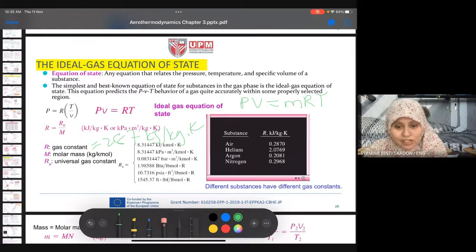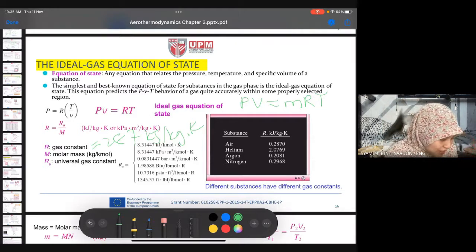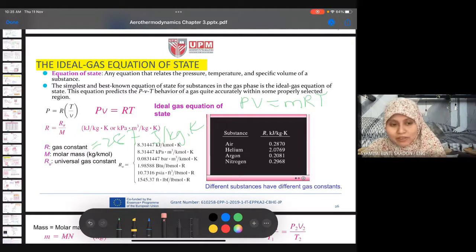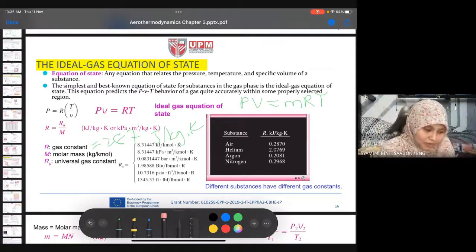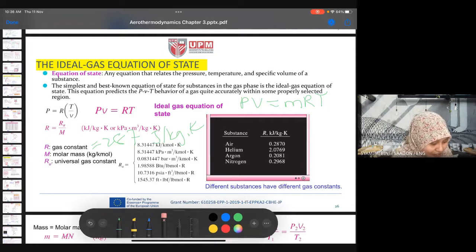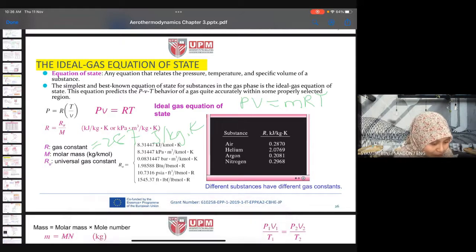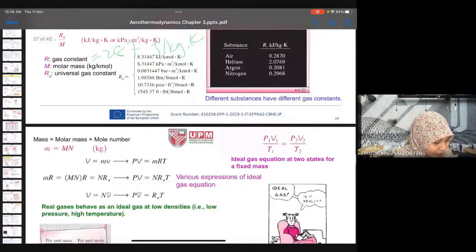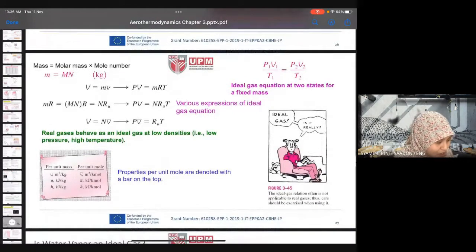Okay, R is 287 joule per kilogram Kelvin, but in kilojoule it is 0.287. Okay, for air, you have to remember this value because you will use it several times often. But usually I will give this value and you can also search for it.